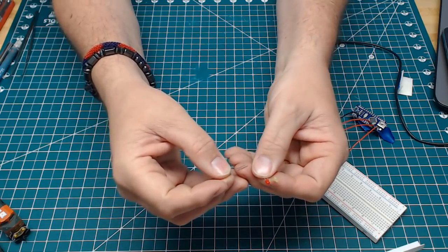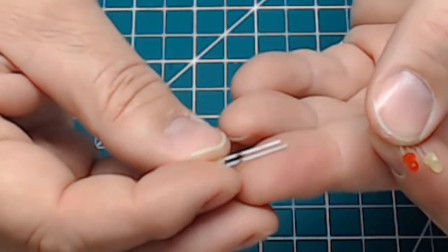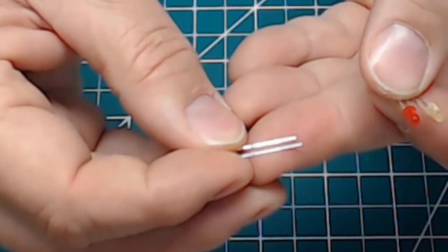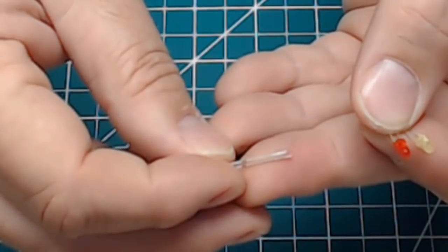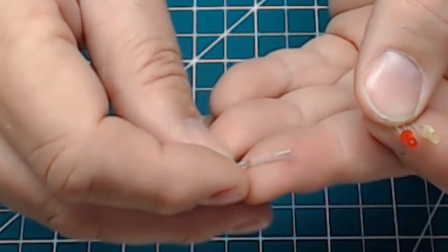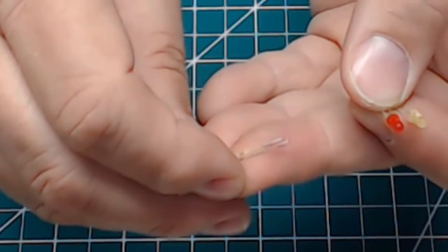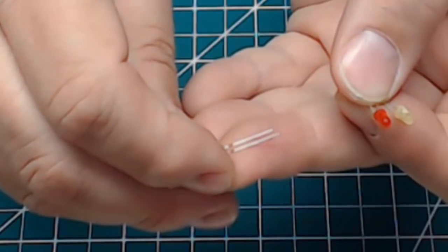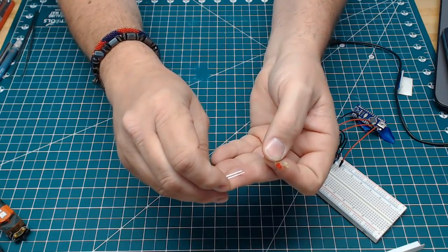Now, if you're not familiar with LEDs, you'll notice that the diodes or the wires on LEDs, one is always or typically a little longer than the other. Pay attention to that because polarity is crucial with an LED. You have to have your electricity flowing the right way, and the longer of the two diodes on an LED is the positive side. So make sure that when you're hooking up your LEDs to your Arduinos, your longer pin hooks to the actual output pin on your Arduino, and the shorter pin will hook to the ground. I always put the resistor on the positive side whenever I hook up an LED.